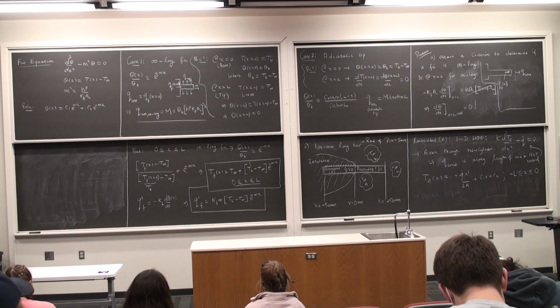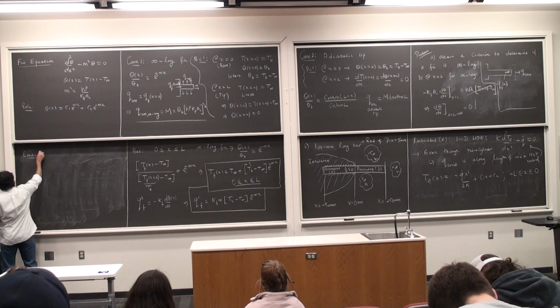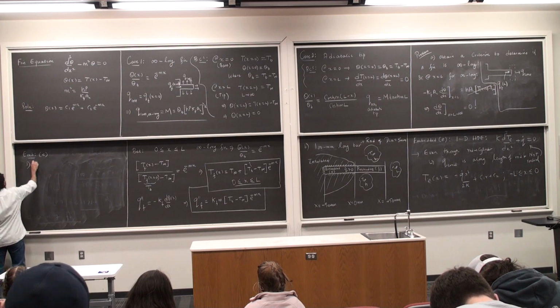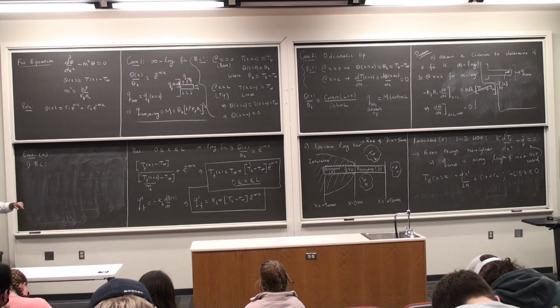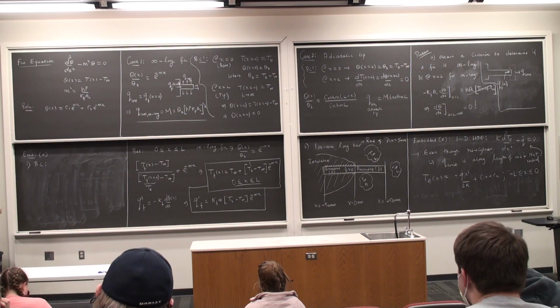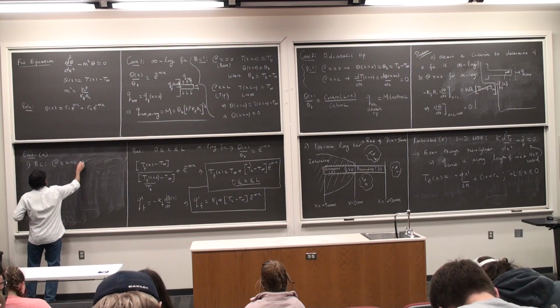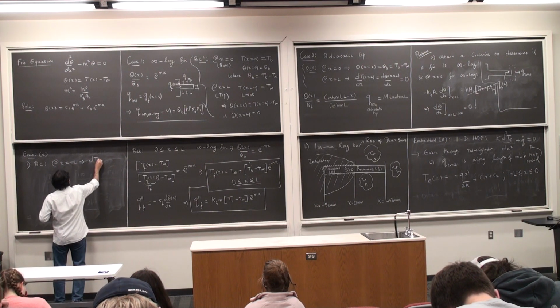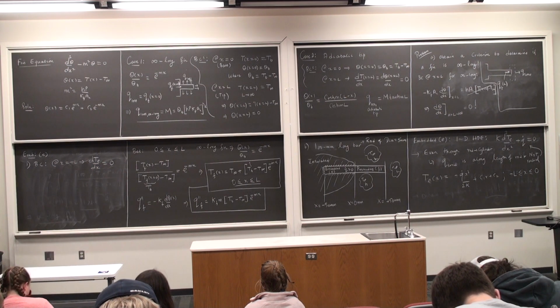Alright, now we start using the boundary conditions. So the embedded portion. First boundary condition, please be careful here, do not say that it is insulated at x is equal to 0, it's at x is equal to minus L. Okay, so at x is equal to minus L, dTE by dx is equal to 0.